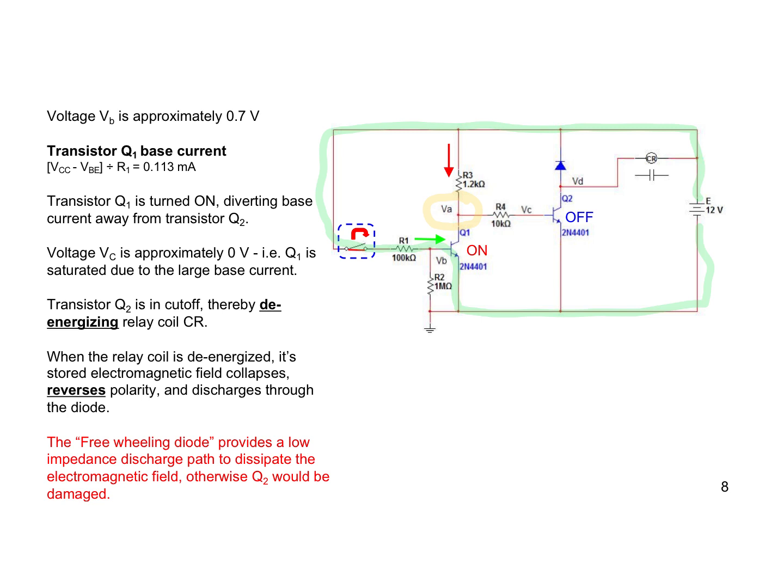But in any way, the current path is down this way, and there's going to be no current flowing through the base here. So therefore, this is off. Of course, the coil is de-energized, and the contact is in its normal rest position. So, okay, you can have a look at that. That's all the important stuff.